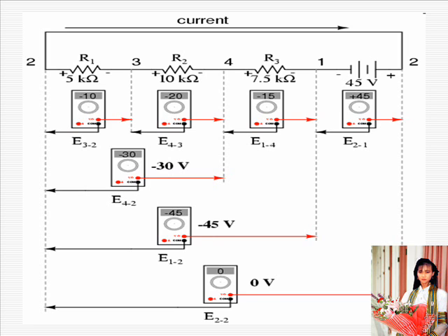The fact that series voltages add up should be no mystery. But we notice that the polarity of these voltages makes a lot of difference in how the figures add. While reading voltage across R1, R1--R2, and R1--R2--R3, I'm using a double dash symbol to represent the series connection between resistors R1, R2, and R3.